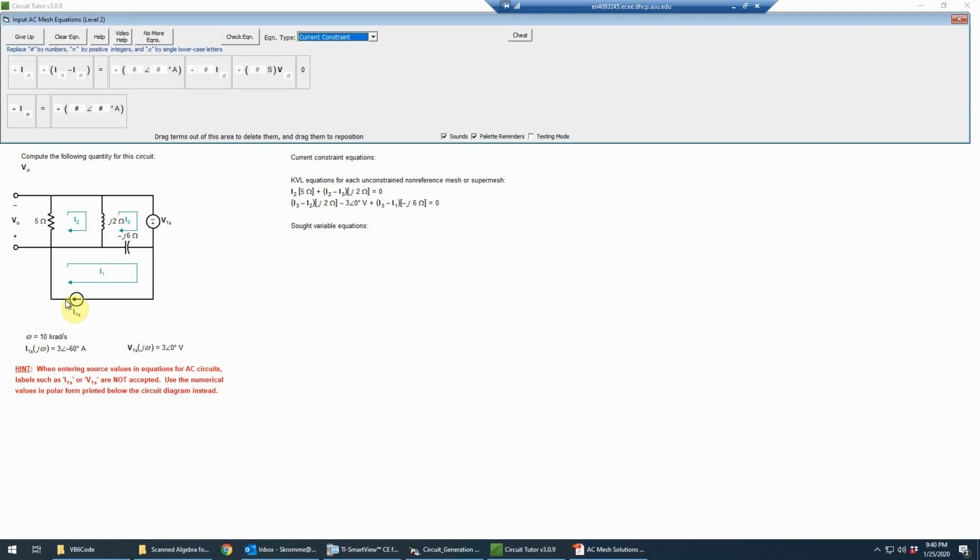So we set that equal to a fixed value, and as I said, we won't need a minus sign. Now if the current source arrow were going the other direction, then we would need a minus sign out in front of the complex number. And remember that the magnitude itself of the complex number can never be entered as a negative number, because magnitudes by definition are not negative, but you can precede the entire complex number by a minus sign. That just really means that you're changing the phase angle of the complex number. And you can also do it by changing the phase angle, for example.